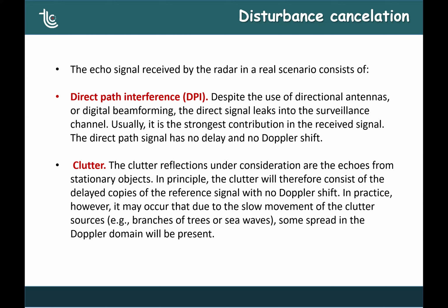In this case, there are the sea waves, so the sea is not still. It means that the clutter has some internal movement, so there is some Doppler shift in the clutter. Okay, so it is possible that there is some spread in the Doppler domain.